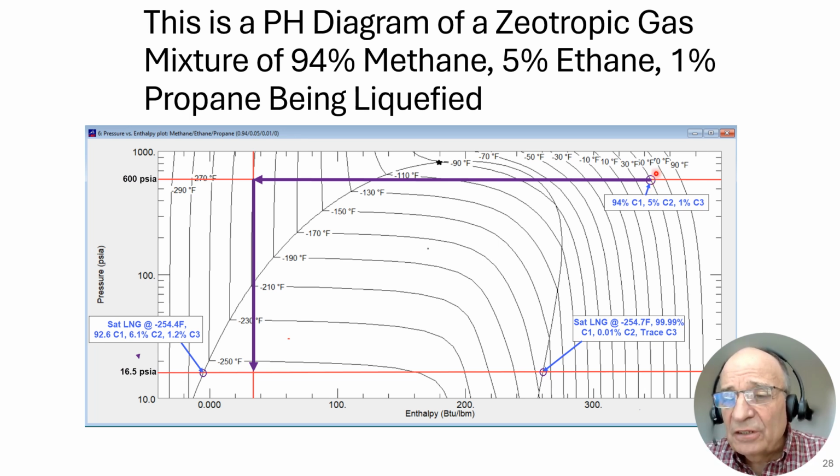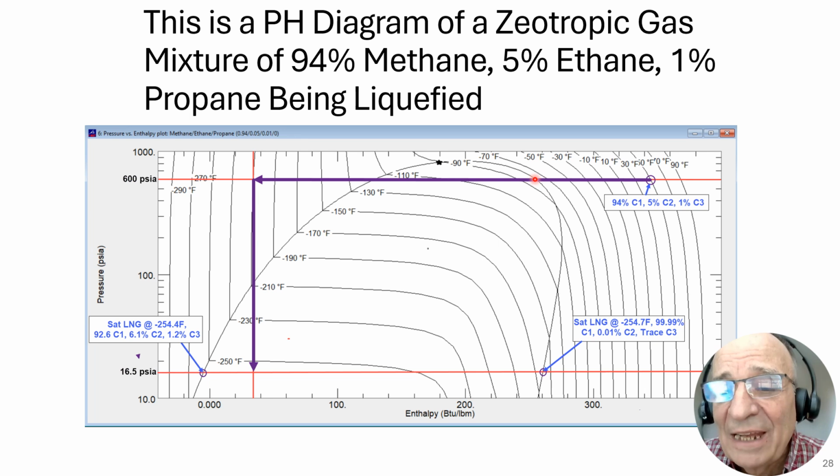So you have this mixture of natural gas that's been cleaned up, meaning the CO2, water vapor, mercury, hydrogen sulfide, and any other contaminants, solid contaminants have been removed. Heavy hydrocarbon removed, gets put back in, the gas gets put back in, and the process continues along. So let's take that gas and cool it, cool it down. And what happens here? The very first droplet forms.